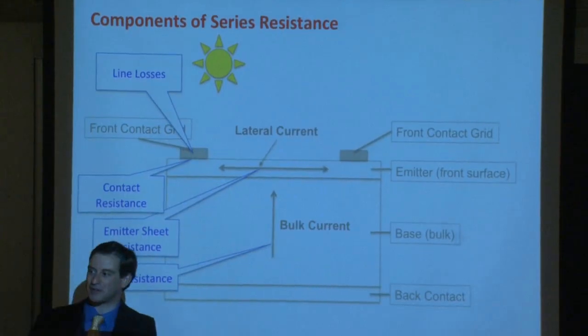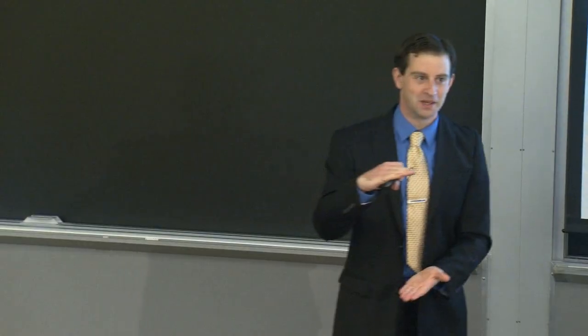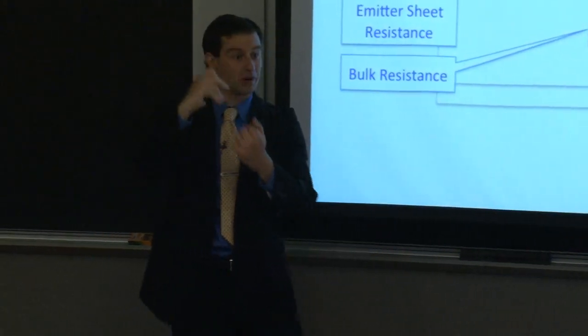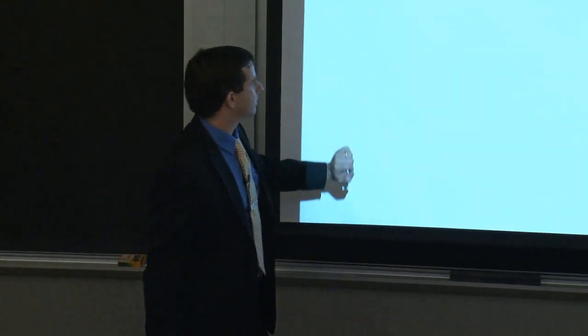We also have to worry about the finite resistance of the bulk material, and we have to spec the thickness accordingly so that we don't wind up with too thick of a bulk material and the series resistance component will be too large. So how to choose the appropriate absorber thickness? Let's talk about that for a minute.